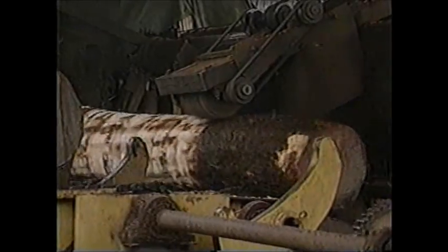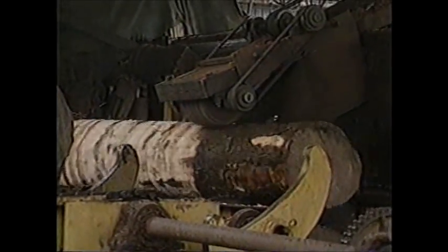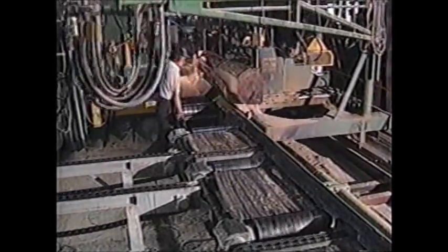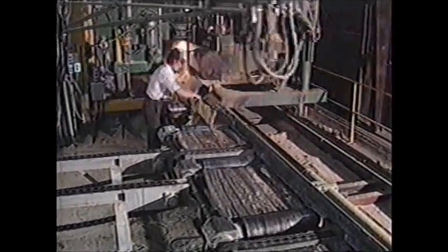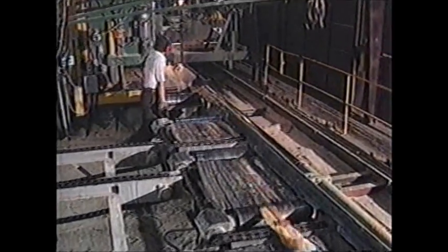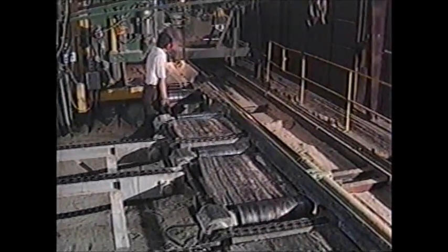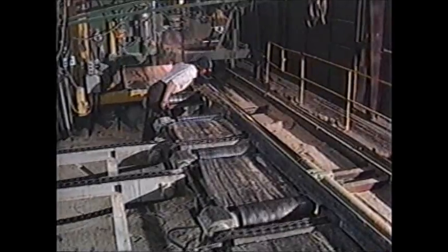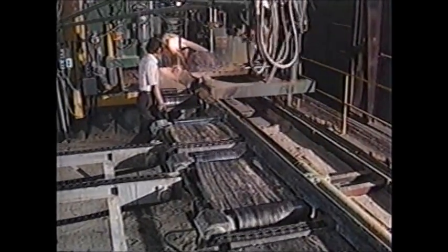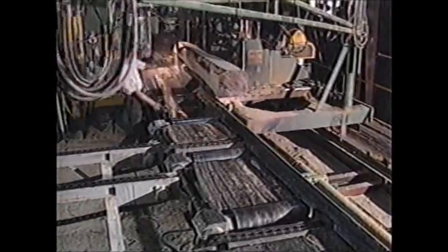Hardwood veneer logs and veneer are both very valuable. This plant employs a bandsaw to break down the debarked logs into half-log or quarter-log flitches. Slabs are first removed to produce a squared-up log. The log is then sawn into halves or quarters.